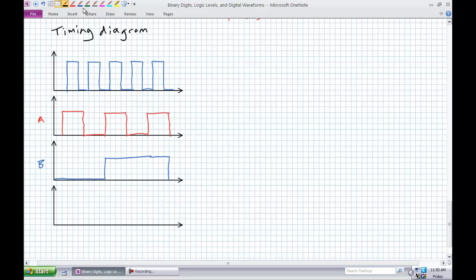How you do that is with what's known as a clock. Clocks are very important to digital systems, and they'll become especially important in sequential logic systems, which we'll go over later. They coordinate the activities of the system and synchronize everybody going together. So if I define the clock's positive edge, i.e. its rising edge, as the time when data is sampled, what are the values of A and B in relation to each other? There are positive edges 1, 2, 3, 4, and 5.